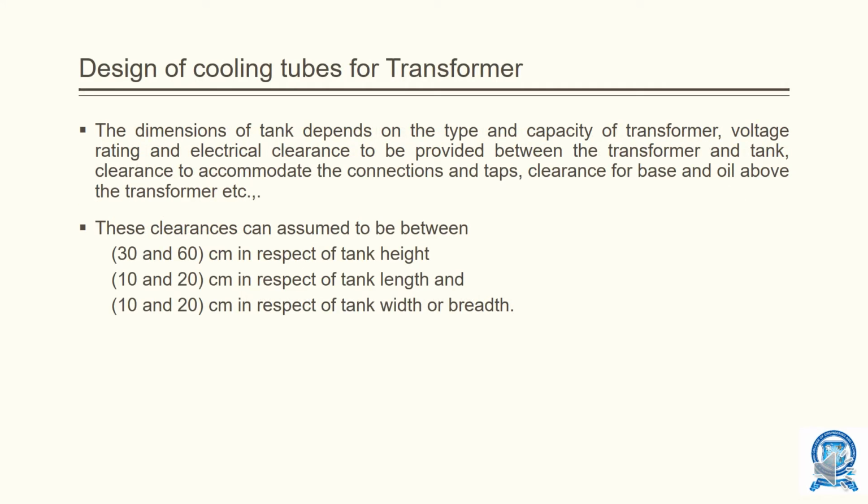Now, how to design the cooling tubes for a transformer in order to cool it down. The dimensions of the tank depend on the type and capacity of the transformer, the voltage rating and electrical clearance to be provided between the transformer and tank, clearance to accommodate the connections, clearance for the base and oil above the transformer, etc.